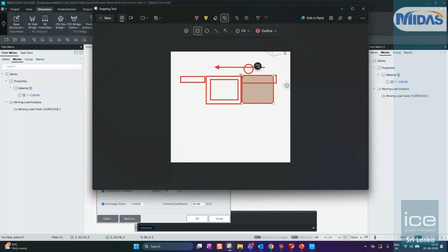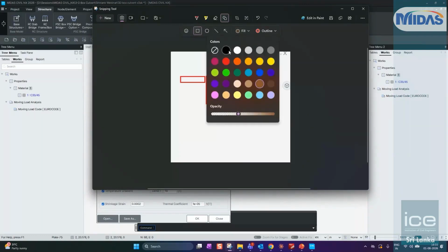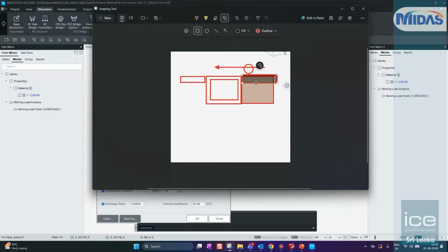This is my soil. After that, your pavement gets constructed, right? Your pavement gets constructed here. So what would happen is that your surcharge, dead load surcharge also got increased. Ideally, this will not always be the case. So that is why if you are accounting for live load surcharge, that should be good enough.